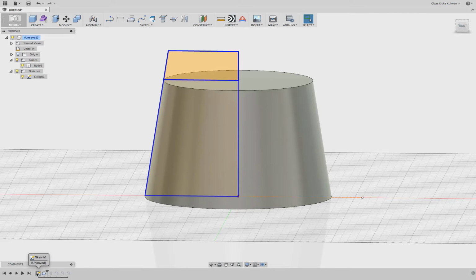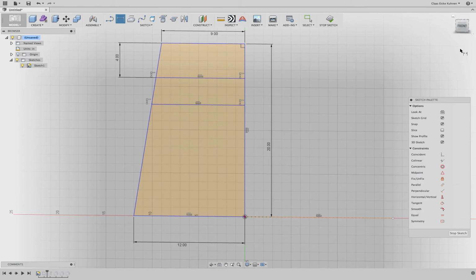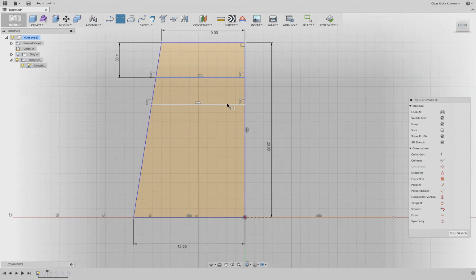So in this case we go back to our sketch, and I will go from here and draw, maybe on purpose, a line to there. You see the line is coincident to these edges, but it is at a terrible angle. So I'll simply put in a horizontal constraint. Let's say the top part has to be strong, so maybe a dimension between these 2 inches.